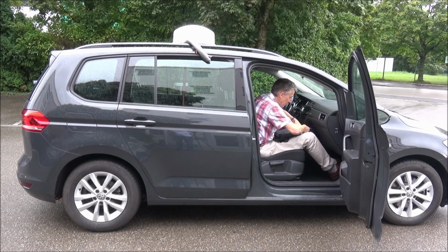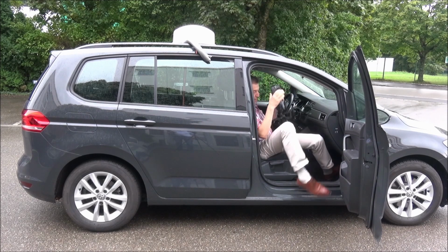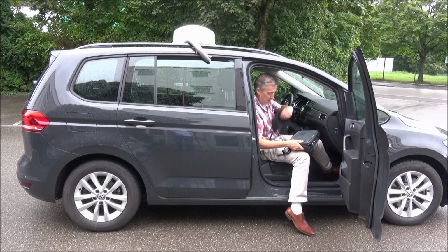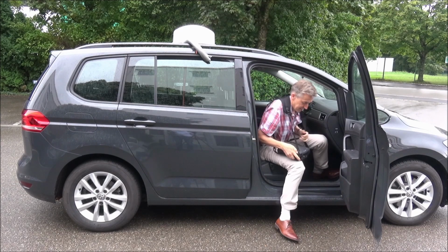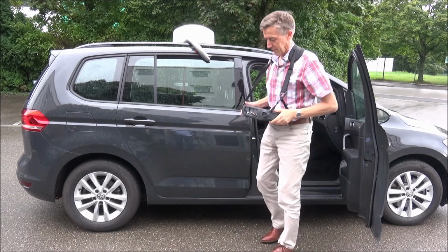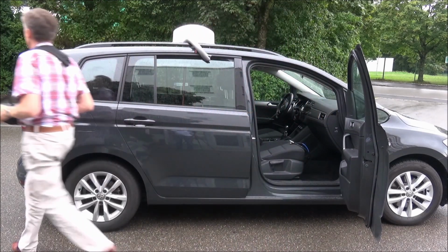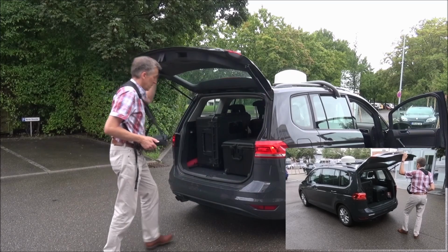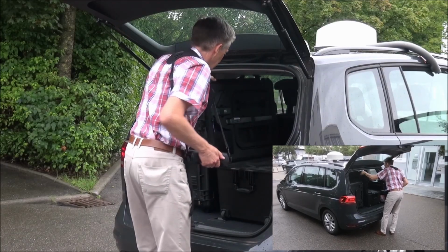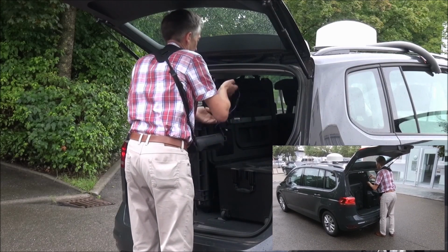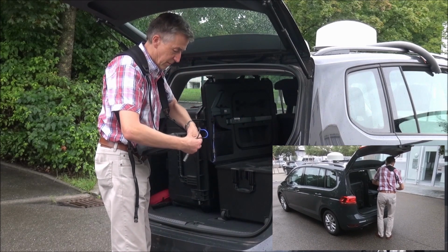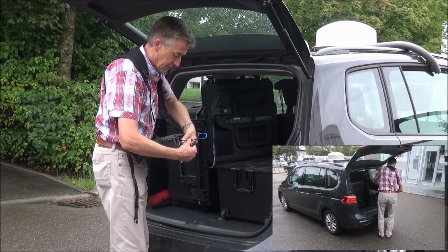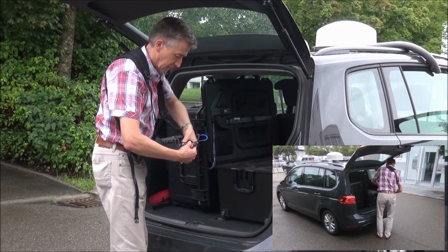Arrived at the point of interest, we disconnect SignalShark from the auto DF antenna, take an adequate directional antenna and proceed the last few meters on foot. Note that our suspected area in this case has a width of approximately 50 meters. Even so close to the signal source, taking bearings with directional antennas on foot, particularly in urban environment or in buildings, can be tricky due to reflections and shadowing.